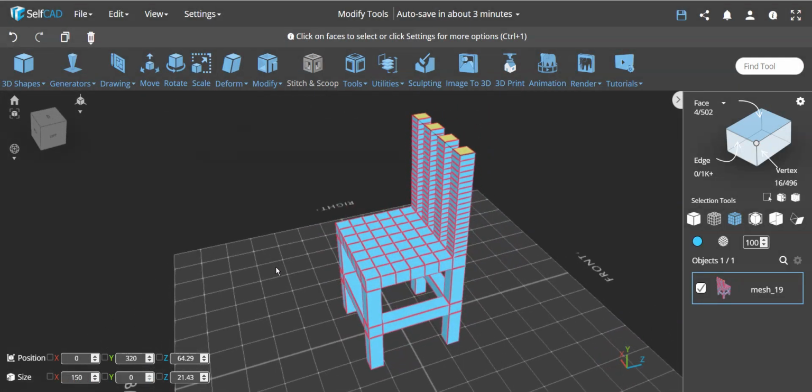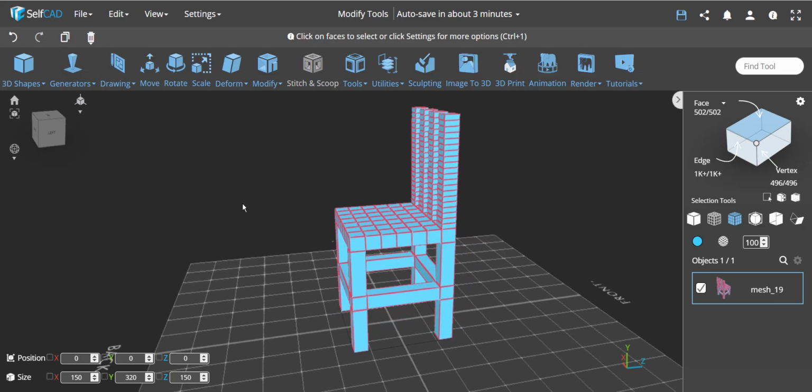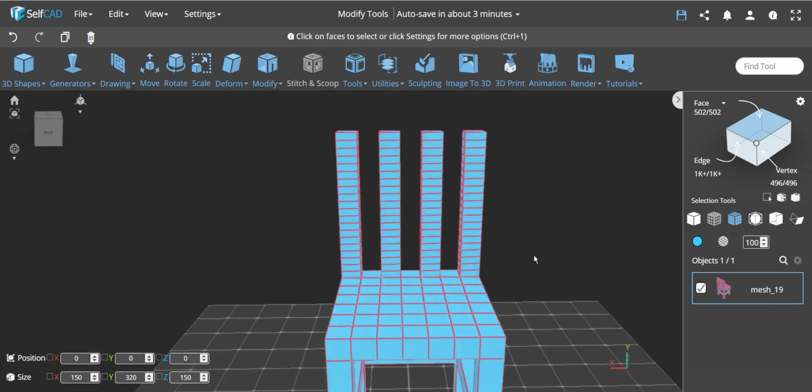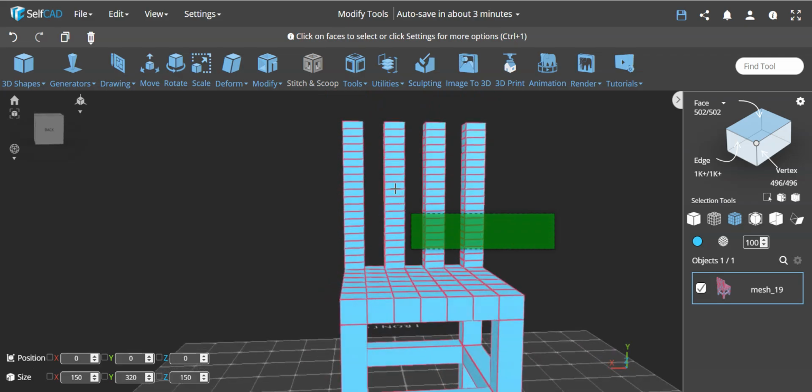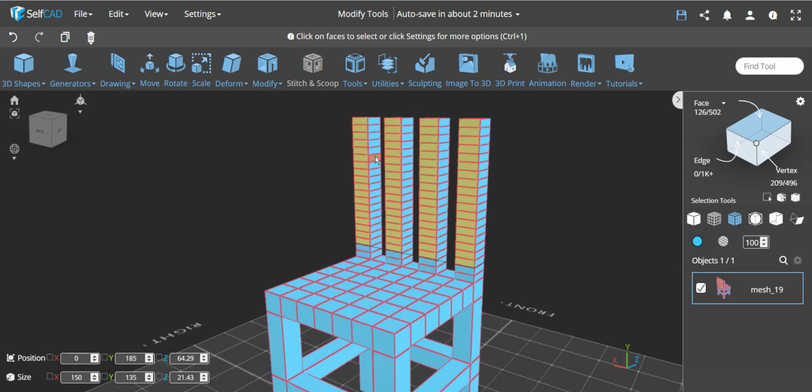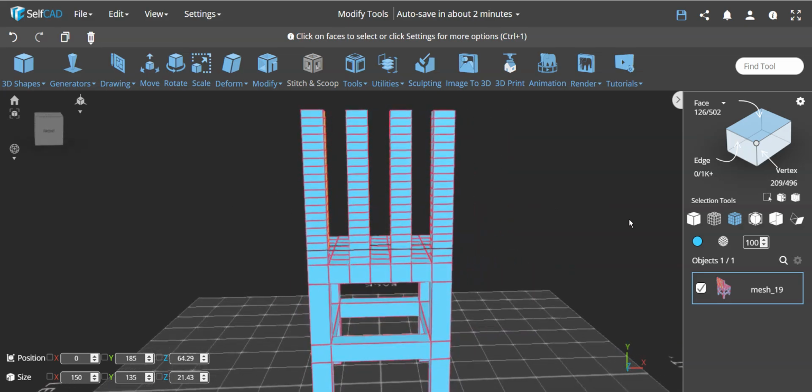So we get now this. I'm deselecting this, and I'm going to select all of these faces. Here I want to show you another concept, which is how you can use marquee selection. Now marquee selection, I've shown it in another video, will select everything that is visible. In this case, these faces are visible, some side faces, like this angle was side visible here, not. Some front faces, but none of the back faces.